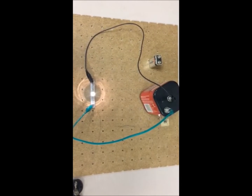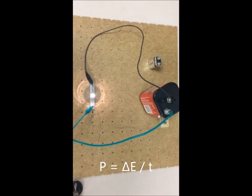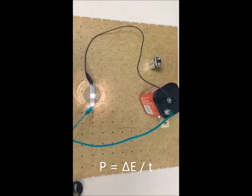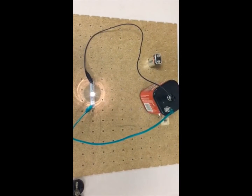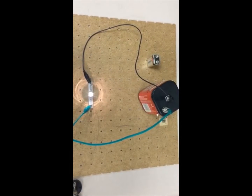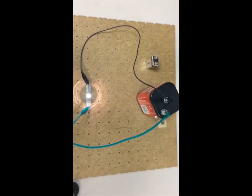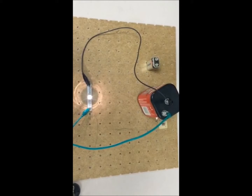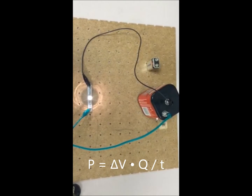As such, the generic equation for power is P equals the change of E over t. The energy lost or gained is simply the product of the electric potential difference between 2 points and the quantity of charge which moves between those 2 points in a time period of t. As such, the energy lost or gained is simply the change of V times Q, which is the charge. When the expression is substituted into the above equation, the power equation becomes power equals the change of V times the charge over t.